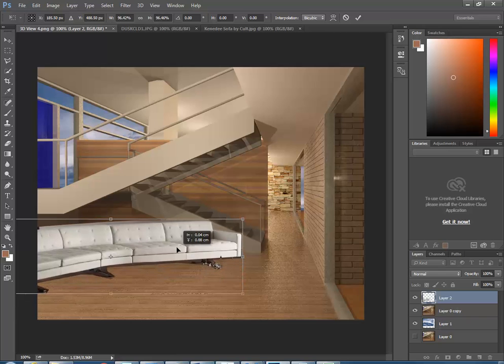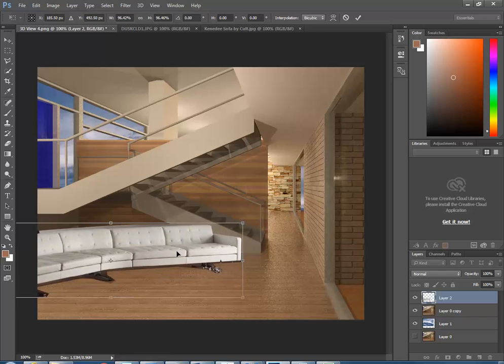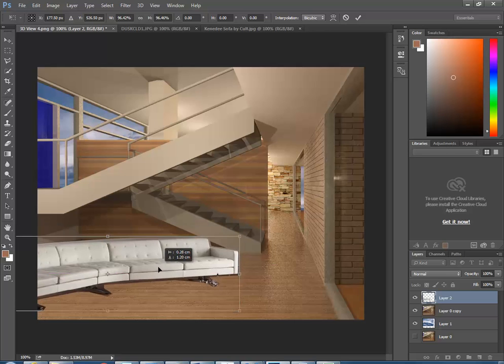Okay, so a good option here might be to put in something that is just the same shape in plan. So just a very rough outline that you could do with an extrusion that goes straight up, and stick it in the perspective view just to line this up a little bit better. But that would do as a starting point.